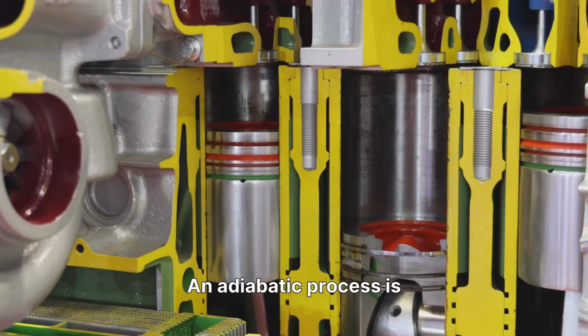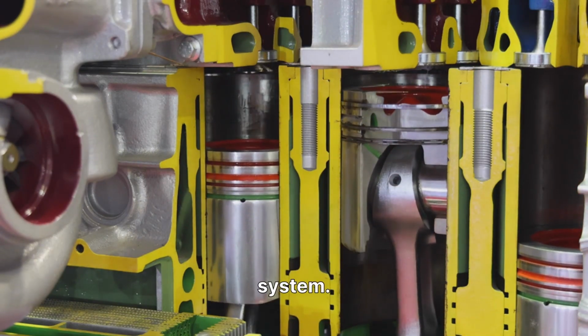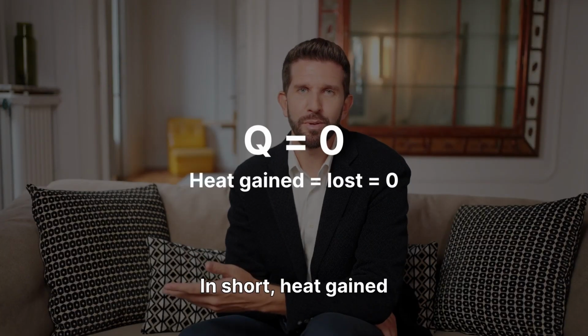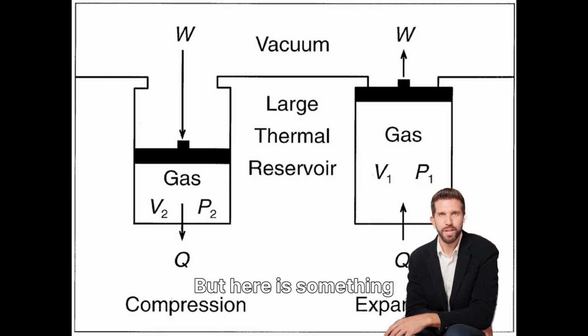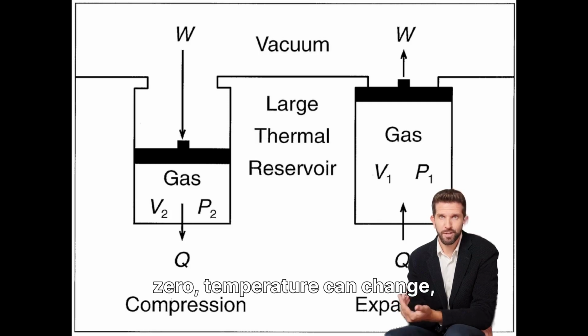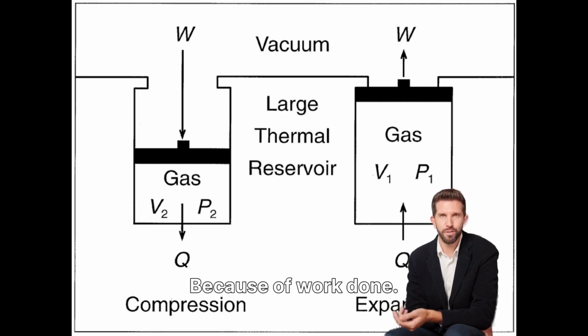An adiabatic process is a process in which no heat enters and no heat leaves the system. That means there is zero heat transfer. In short, heat gained is zero. Heat lost is zero. In equation form, Q equals zero. But here is something interesting. Even if heat is zero, temperature can change, pressure can change, volume can change. Why? Because of work done.